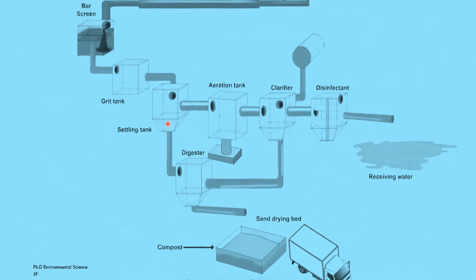Then waste such as oils, soap and grease rise to the top of the wastewater, and the waste material that settles down at the bottom is known as sludge, and the floatable material is called the scum. Scum is then removed using a skimmer, and sludge is removed with a scraper every few days. The water that is left out is called the clarified water.